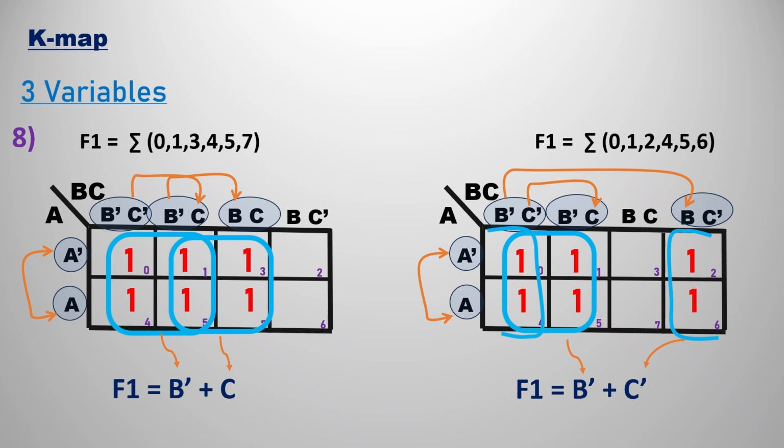If you see the second K map of 3 variables, that is 0 1 2 3 4 5 6. As we already saw, 0 1 4 5 is a group. And we also have Karnaugh grouping in this, that is 0 4 2 6. As A is changing, ignore A, and you only consider the B bars and C bars.